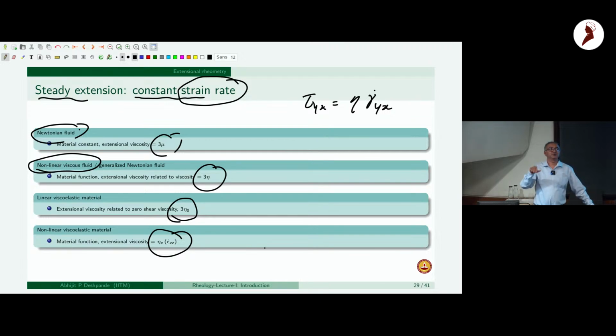So given that's the motivation, now we have to see how we stretch a strand of fluid. It's experimentally more challenging to do such stretching, because one, you need much finer control over much longer distances. Rotational rheometry, on the other hand, is in a confined space, while once you start doing stretching-type experiments, you start getting control issues, but it has become better.